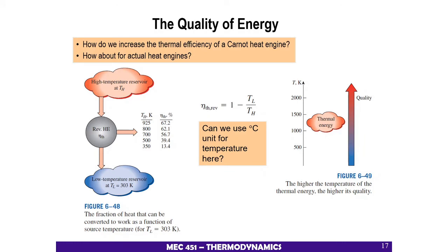The quality of energy. How do we increase the thermal efficiency of a Carnot heat engine? How about for actual heat engines? That is the question we normally ask when dealing with Carnot engines. The efficiency for a reversible engine is 1 minus temperature low divided by temperature high.